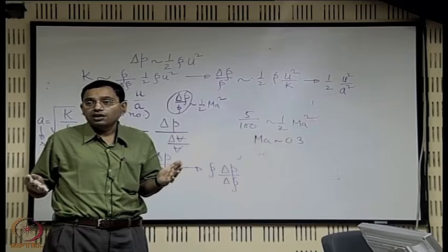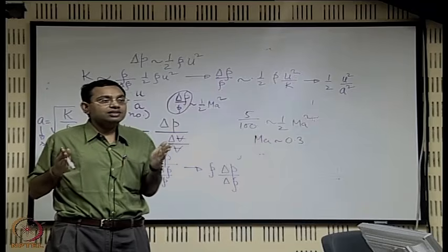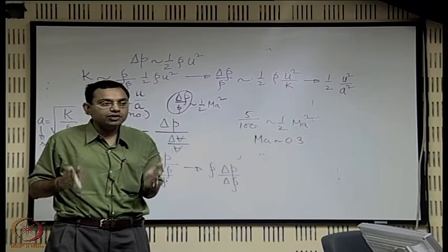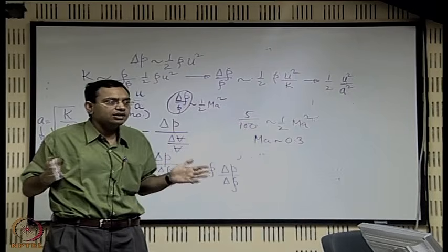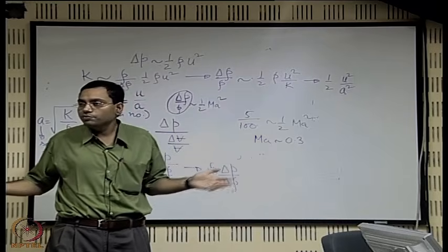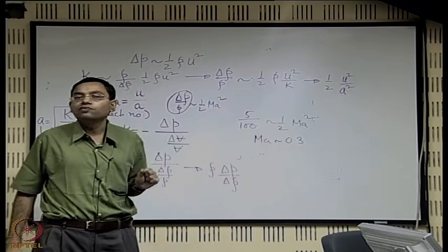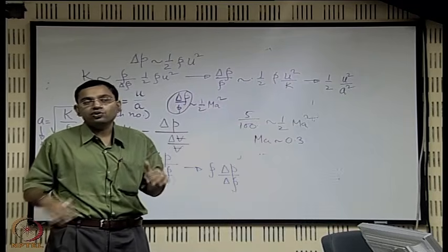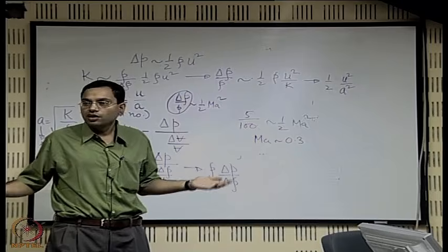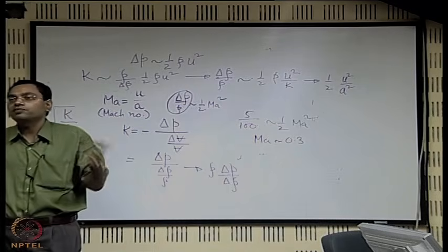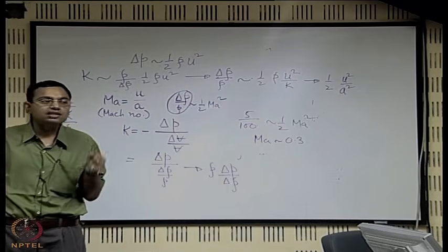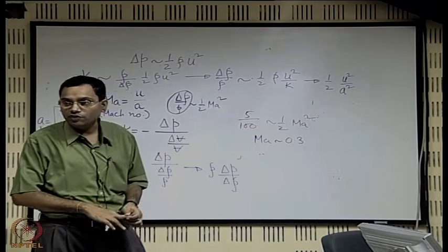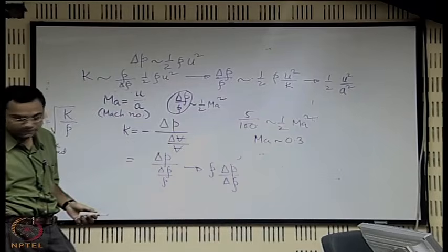Compressible flow means a fluid element which is going to have a volumetric strain or change in volume per unit volume by whatever reasons, it need not be just due to pressure, it may be because of anything, then we say that it is a compressible flow. So, compressible fluid and compressible flow are related because of course one of the reasons for a flow being compressible is because the fluid itself is compressible. So, the density change due to change in pressure is significant, but there could be other effects that are creating the change in volume. So, this is a concept that we should remember.